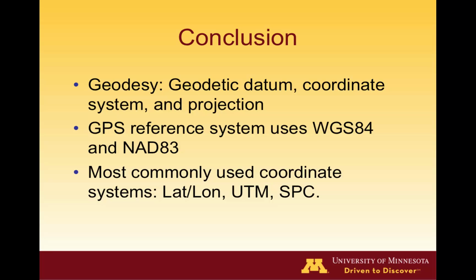So a coordinate system requires this datum. That's why when we try to transfer the UTM to the latitude, longitude, and height system, they ask us to choose if it's based on NAD 83 or WGS 84 or NAD 27.